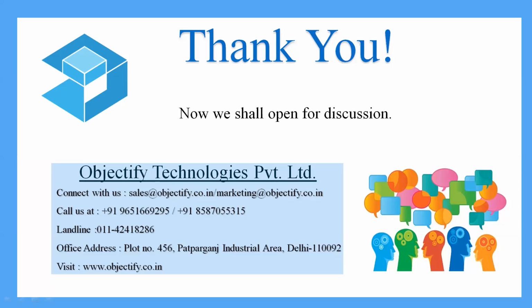Feature-based modeling or parametric modeling is very easy for engineers and designers to alter certain features. So once you convert to STL, going back and editing is much more tedious. You can do it only using the CAD modeling software. But people are looking for software packages and file formats where they can do last minute editing as well. That's why one format called 3MF is being developed, where you can edit certain features at the last moment. And AMF format is another similar sort of approach. And on top of that, as I mentioned, it's elevating the game.